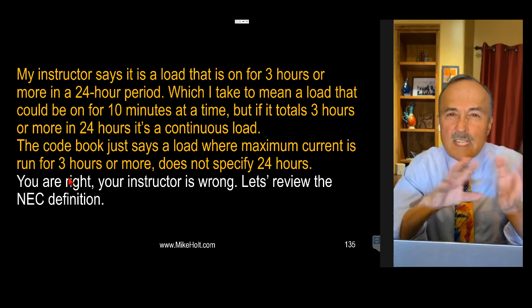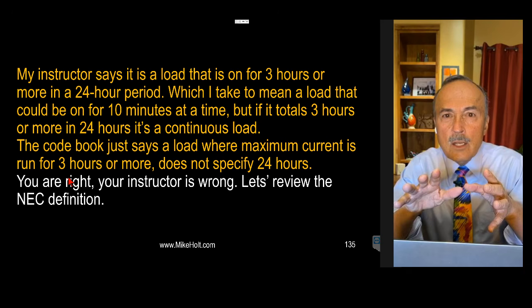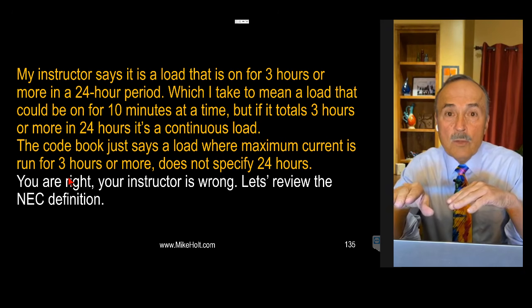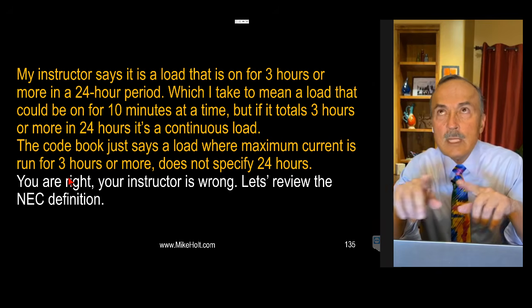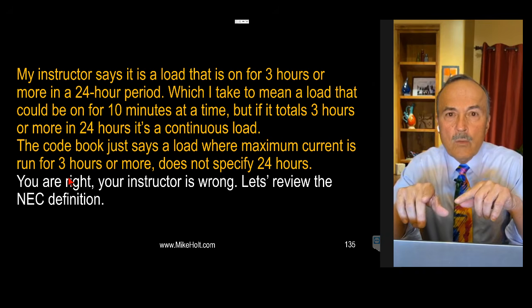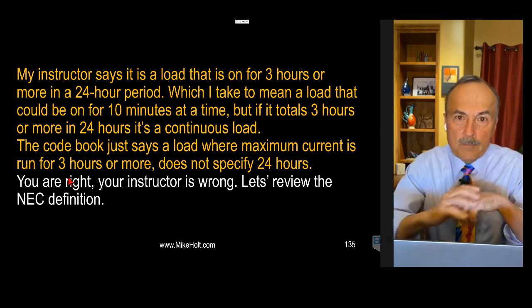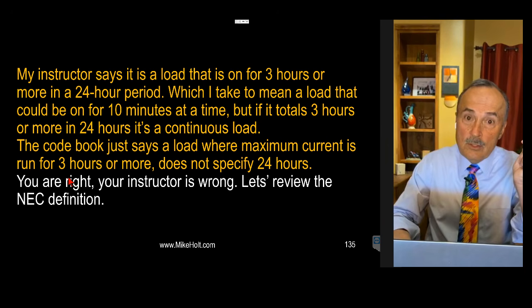Now, we don't use the 80% in the code in reality. What we do is we take the load, as it says in 210.19(A)(1), and also 215.2, we take the load at 125%, then size the wire and size the breaker. So that's what a continuous load is.